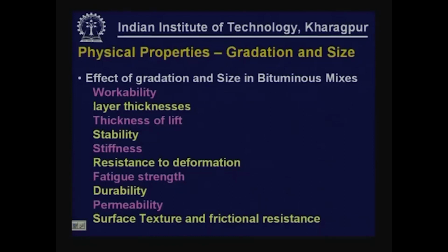The fatigue strength of the mixes gets affected by the gradation and size that we use. Even the durability gets affected. The permeability of the mix changes with gradation and maximum size, and they also affect the surface texture and frictional resistance of especially the surface bituminous layers.